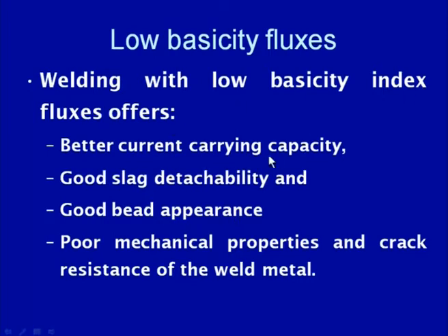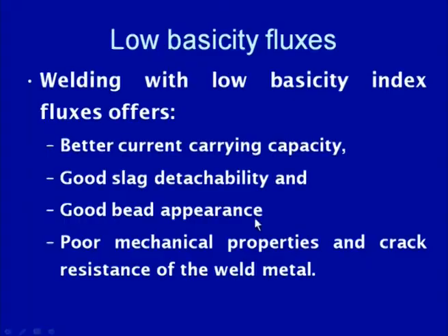So, the low basicity fluxes offer the advantages of better current carrying capacity, good slag detachability and good bead appearance, but the mechanical properties are found to be poor, and poor resistance to crack development is also noticed.